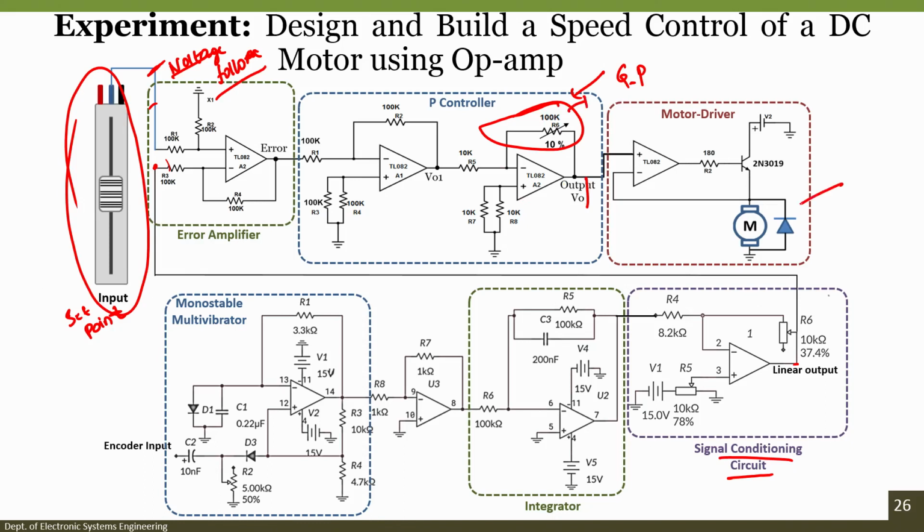But as per the specifications of our motor, the maximum rated voltage is 6 volts, and we have designed our signal conditioning circuit to operate from 0 to 5 volts. If it is operating at 6 volts, the RPM of the motor will be higher. Again, the chosen resistance R1 and capacitance C1 may not match that value, so some pulses may be missed. Because of that reason, we have restricted our operating voltage to 0 to 5 volts.